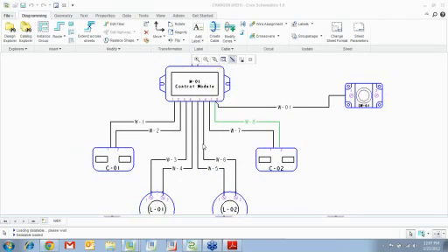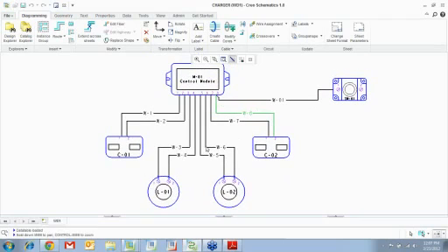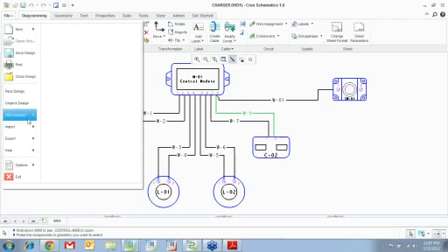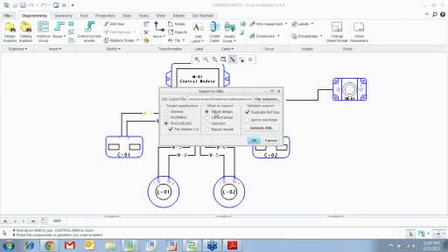All right? So that's how we pretty much create this whole wiring diagram. We added all these symbols, we changed the model name parameter, we went to the ports, we added this entry port parameter for the ports, we routed the wires, and we applied the data set to the wires. Once you do this part, you go File, Export, and you want to export it as an XML file. So you export it as an XML file and you hit OK.